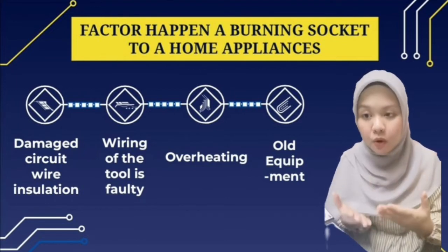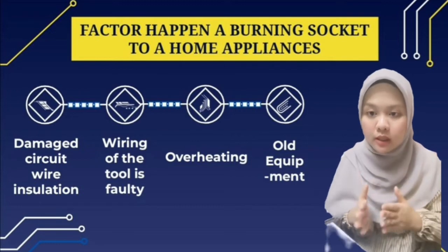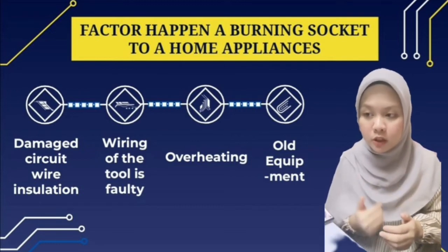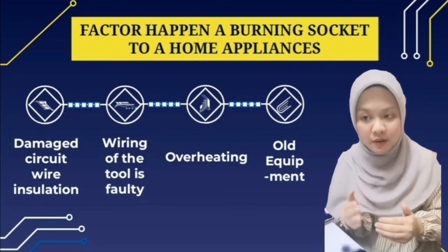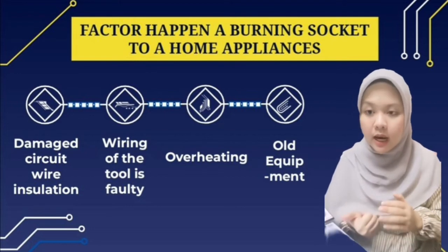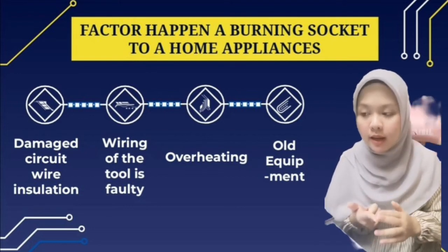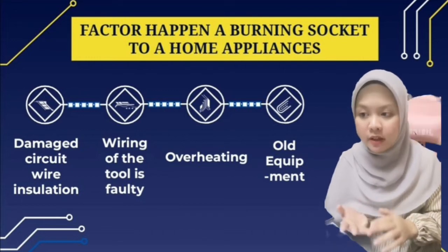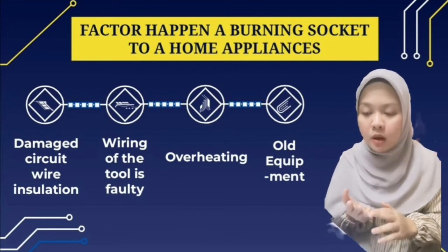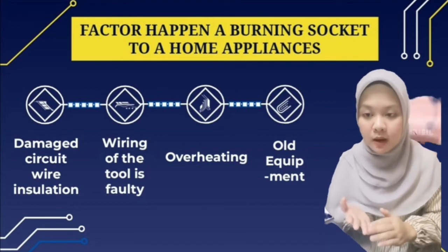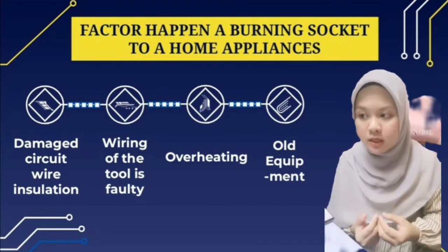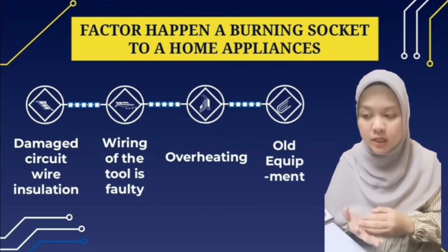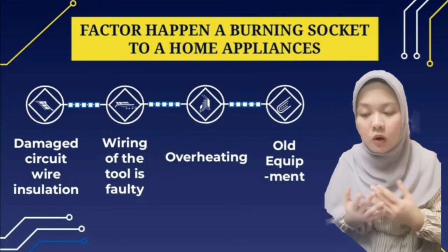it becomes more dangerous when users use all the extension sockets simultaneously with high ampere devices, such as a water heater, rice cooker, iron at 5 ampere, refrigerator at 3 ampere, and portable air conditioning at 5.5 ampere. Supposedly, the MCB C20 will trip due to overload.